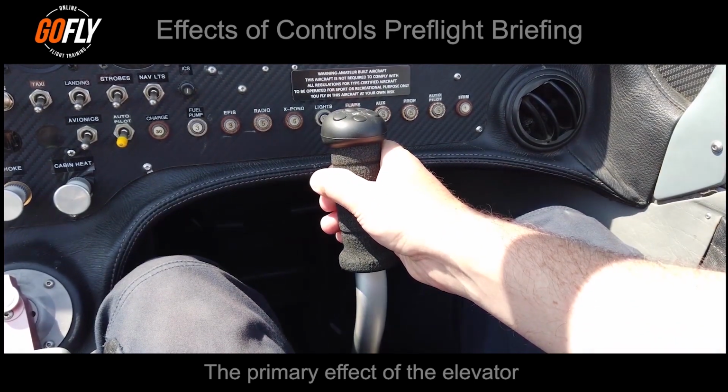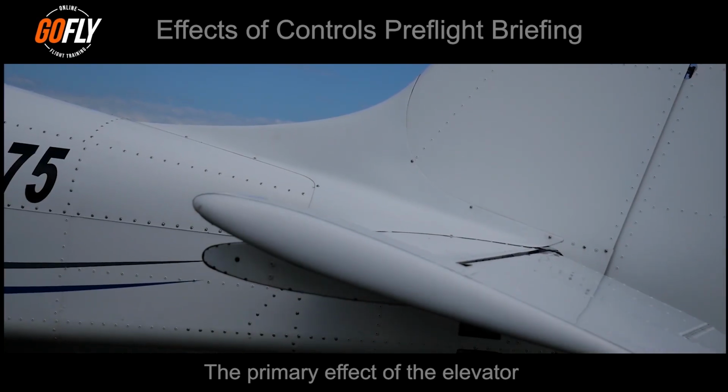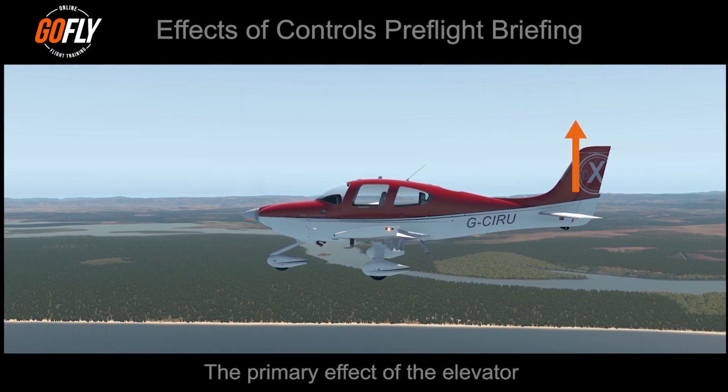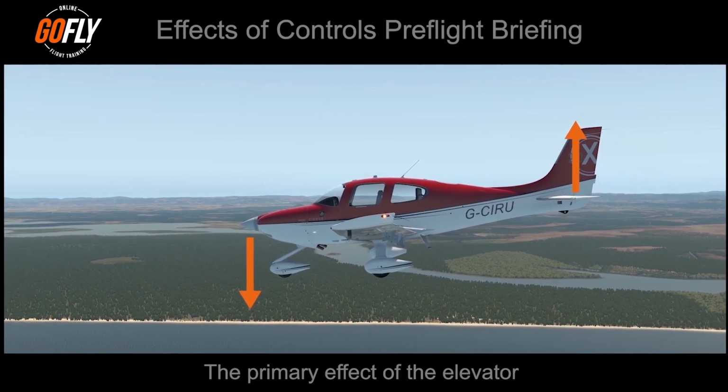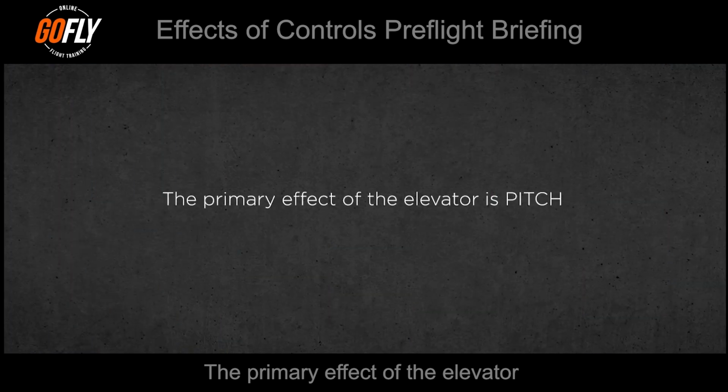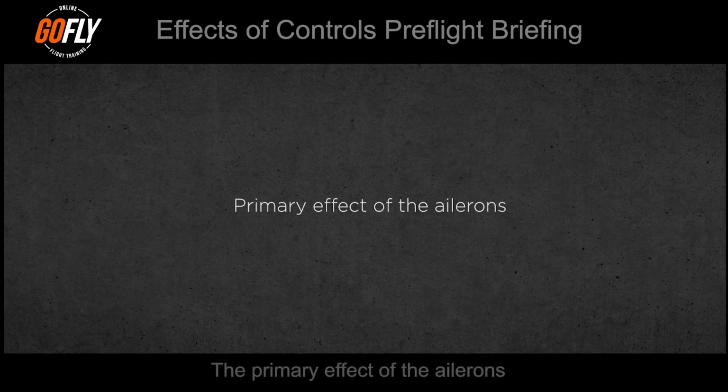When you move the control column forward, this deflects the elevator downward. This deflection causes an upward force that moves the tail up and therefore pitches the nose of the aircraft down in relation to the horizon. The primary effect of the elevator is pitch.